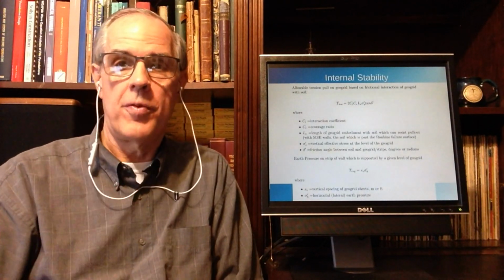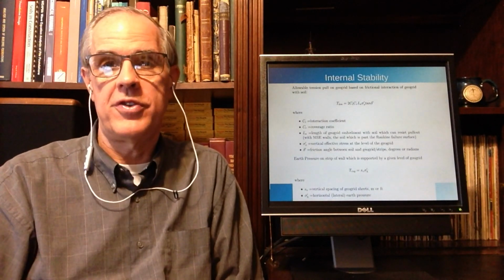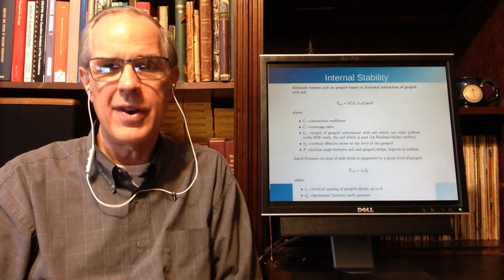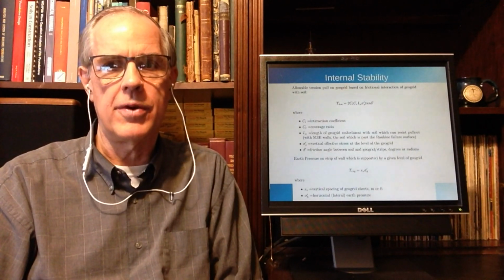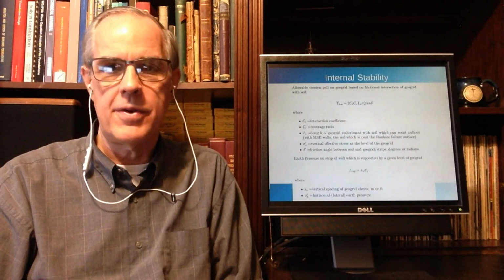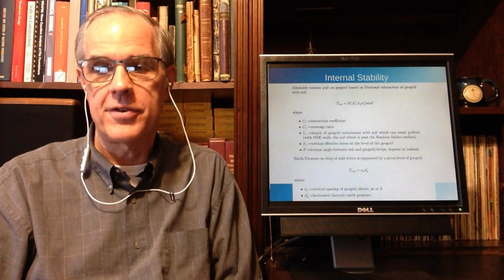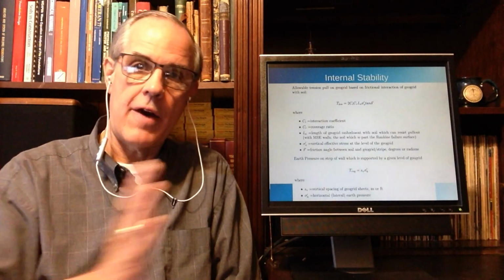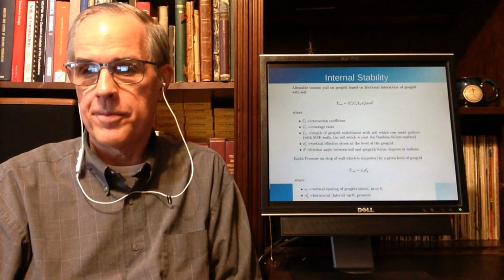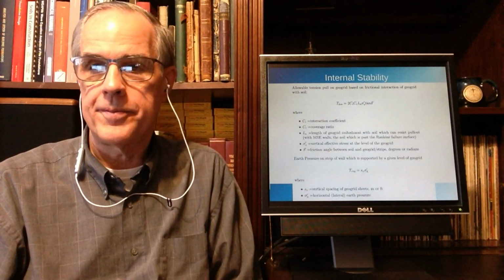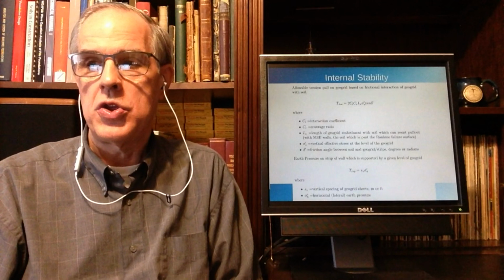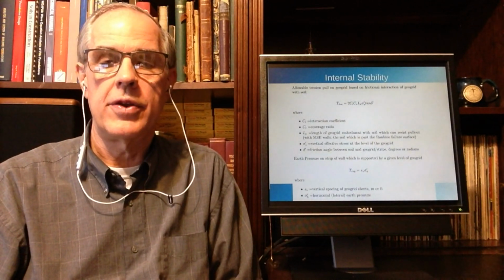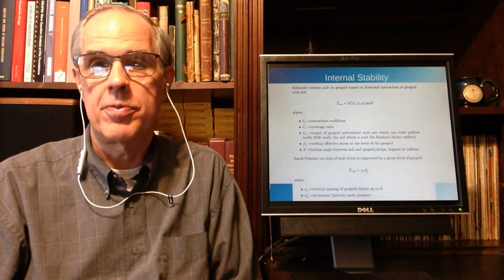If you have uniform spacing, those two are the same. If you don't have uniform spacing, and sometimes you don't, then you have to compute SV for every layer. It's going to be different. And then sigma prime H is the lateral pressure against there. If you do the units on both, you will end up with kilonewtons per meter of wall or kips per foot of wall.